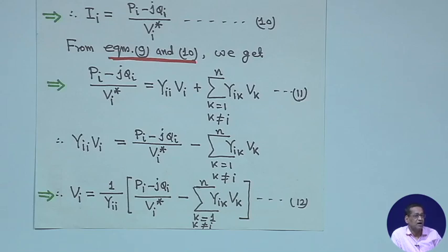So its convergence is much faster than the Gauss-Seidel method. In Newton-Raphson, the number of iterations is almost independent of the dimension of the problem. But in the case of Gauss-Seidel, if the dimension of the problem increases, then naturally the number of iterations is also much more. We will see that later, but the convergence characteristics, linear for Gauss-Seidel and quadratic for Newton-Raphson, are beyond the scope here.